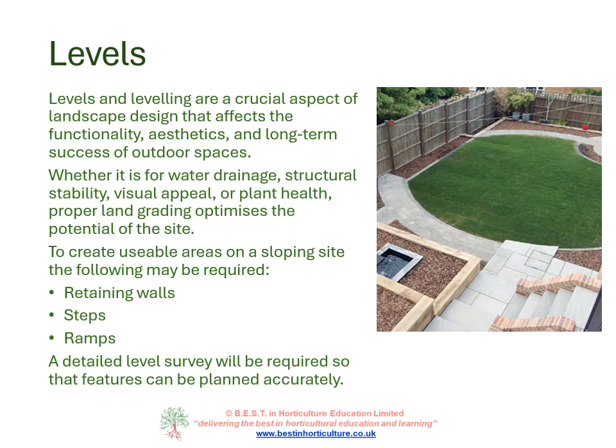It can be quite deceptive. Many sites that look relatively flat can, on conducting a level survey, reveal quite a fall across the land, resulting in the need for unexpected steps or raised beds or other structures. So it always pays to pay attention to the levels on a site.